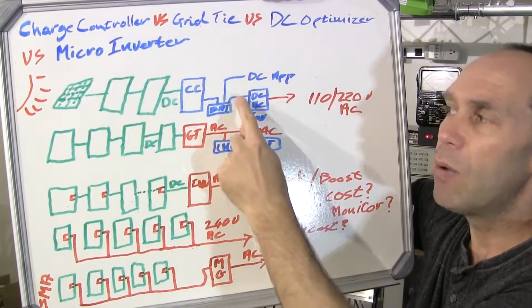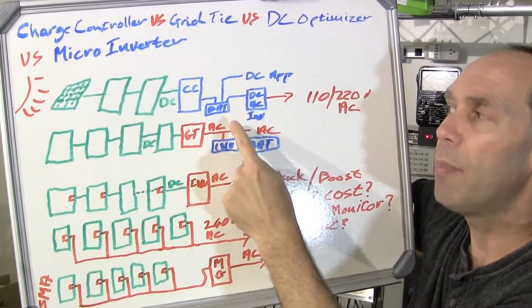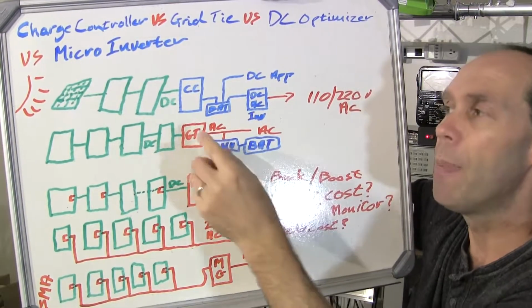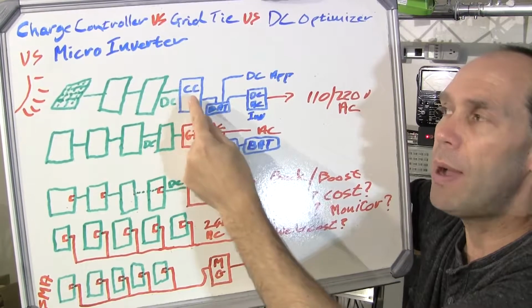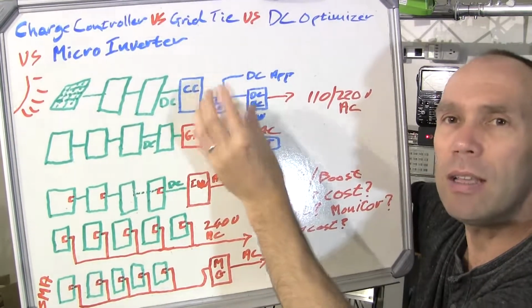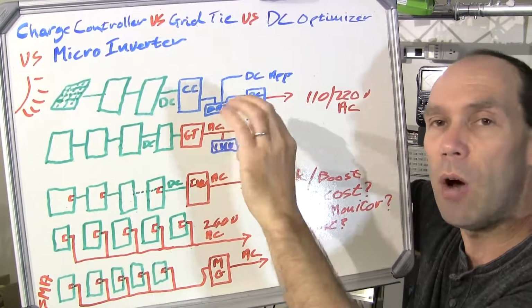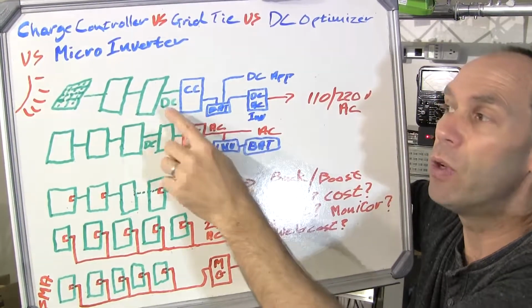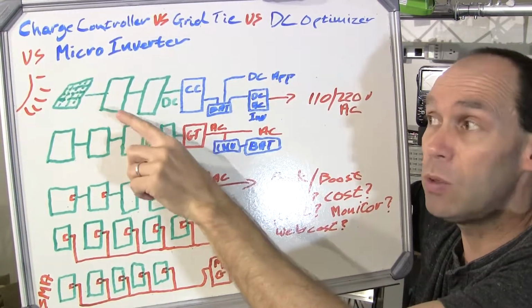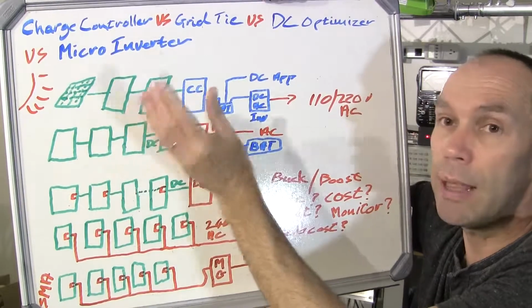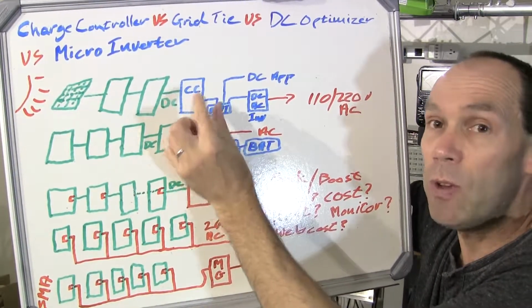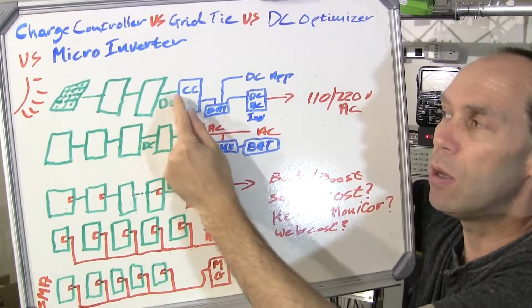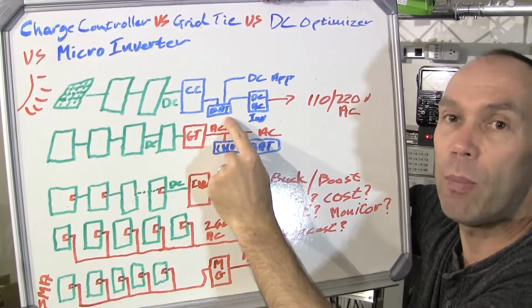In a system, let's say we've got a 48 volt system where you might be feeding into an inverter, then you're obviously going to want your voltages coming out of your solar power system and into your charge controller as close to that as possible. Obviously, it's going to do the DC to DC conversion to optimally run the solar panels using MPPT to get their maximum power point, but then convert that voltage, which is hopefully close enough so there are not too many losses, to, let's say, run your 48-volt battery system.